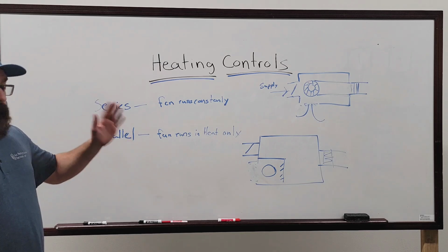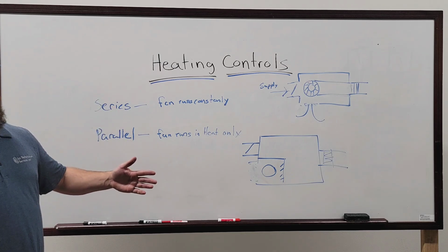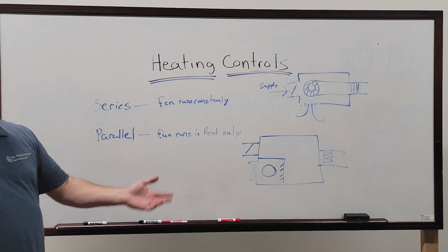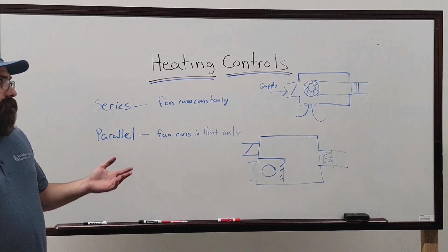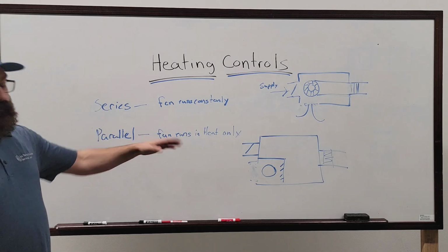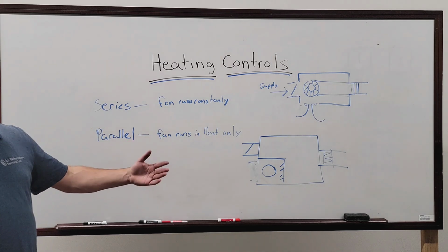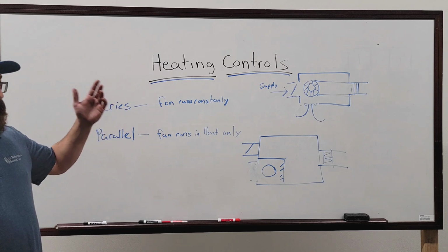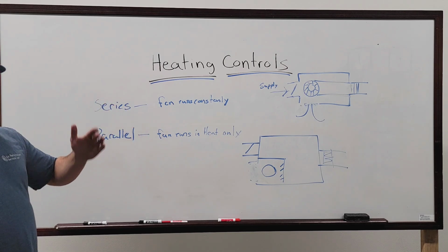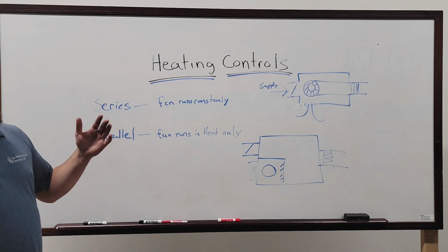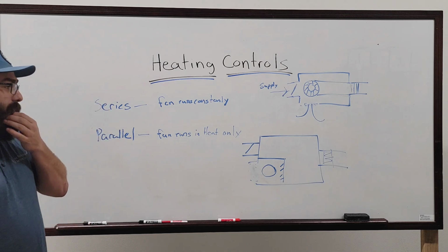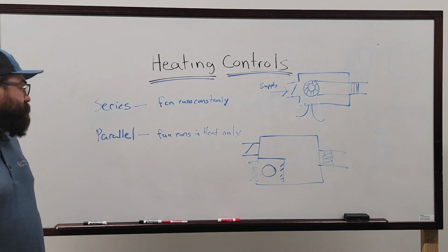Your damper's gonna go to a minimum and your fan's gonna kick on. That minimum may still be 10, 20% depending on what the engineered value is, but it can also be 100% airflow value and no fan in cooling mode. Whereas in a series box, the fan is always running. You're always modulating between your high and low value for set point, for airflow, and the fan makes the rest up through the plenum. Yeah, so that's that on that.